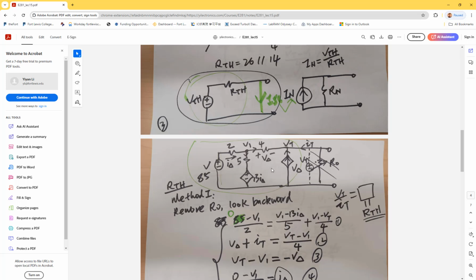So which ones are developing power? You don't know yet. You have to use the mesh current method to find out. Use the sign convention we have been using: if the current is injecting into the plus sign, it's absorbing. If it's delivering, the current is going out from that plus sign, right? Use the mesh current method to find out which ones are developing and calculate all the developed power, and also calculate the power consumption of RO. Could RO by any chance be developing power? No, resistors are always consuming, absorbing. Keep in mind, resistors are always consuming. So some of the components are developing; you add all the developed power in the circuit, and then divide the power consumed by RO by that overall developed power to find the percentage.